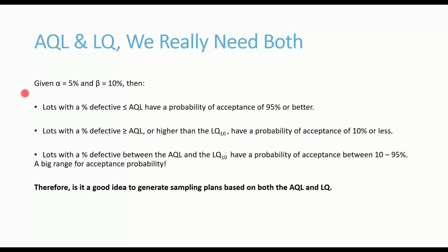If you don't know the protection provided by your sampling plans, a good first step is to document all of your sampling plans, AQLs and LQs, LTPDs, RQLs, right? To document those two things. Then for each sampling plan, you should ask, is this protection appropriate based on past performance and current controls? Sometimes a process changes, right? Or maybe the machinery was updated. Maybe one of the machines is malfunctioning.